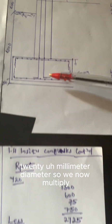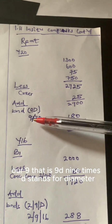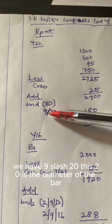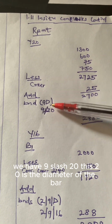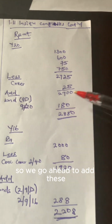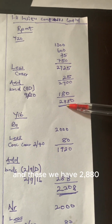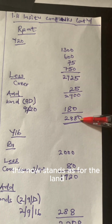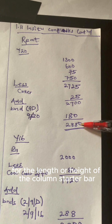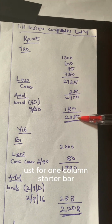millimeter diameter. So we now multiply our 9, that is 9D, 9 times D. D stands for diameter. We have 9 times 20. This 20 is the diameter of the bar. When we multiply this, we have 180. So we go ahead to add this and this. We have 2,880. This now stands as the length or height of the column starter bar, just for one column starter bar.